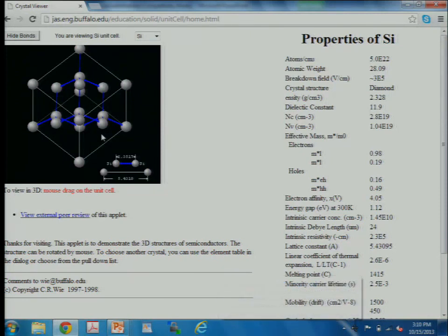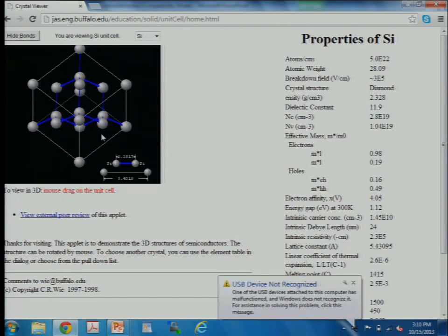All right, so these are actually LEDs inside here, so that's to prove another point later. But basically for silicon at the surface, if you're an OH ion, and you want to grab my bonds, is it easier if they're like this or like this? Right, sticking behind me, right? Like this. So that's why for 111, the bonds that are holding the silicon atoms in place are kind of aimed backwards. So it's harder to form a reaction, to grab the bond, to break the bonds, form a reaction to get the silicon away.